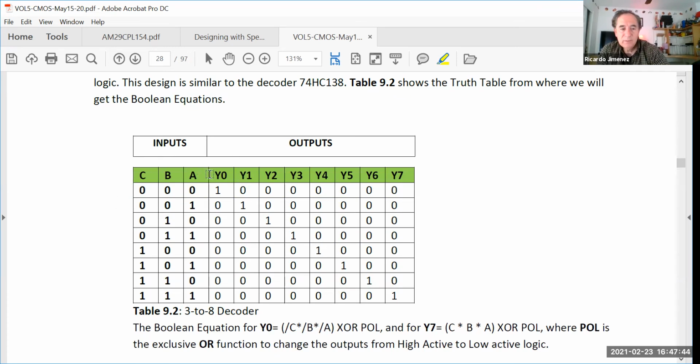Now there is an even higher decoder, 3 to 8. You have 3 inputs and 8 outputs. Notice how, depending on the combinatorial logic right here, you have these or these outputs. Well, I'm sorry for that, I can't erase it. And also here you have this one and this one. So you see the diagonal, all the ones in that diagonal are because you are controlling which one you want to be an output. So you are decoding. That way you can control the data flow.